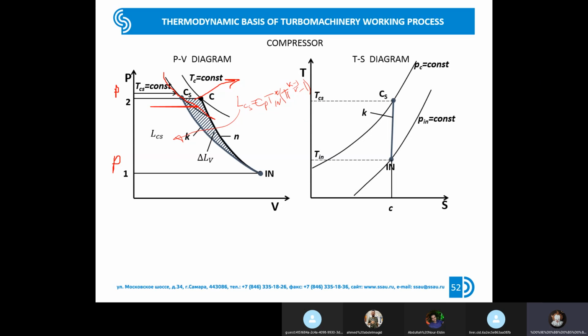So, it's a very famous equation and it's very useful in gas turbine engines and turbomachinery too. That's why I will draw this equation many times. But what's the main information for us at this moment? The work of compression depends on the temperature. And in a real process, because your temperature is higher than in the ideal case, you need to supply some additional energy to provide compression for reaching the pressure ratio which you need.